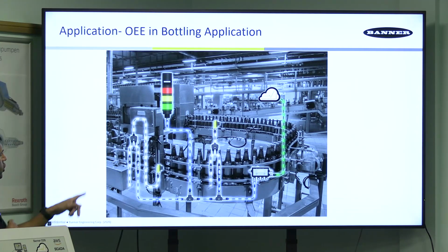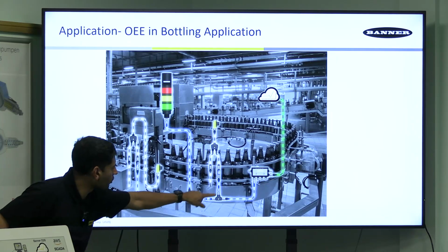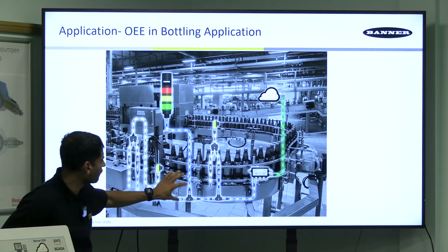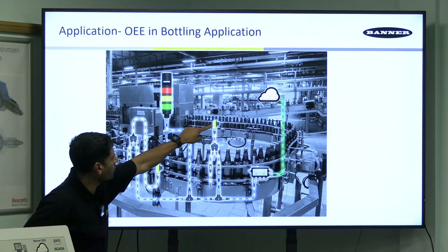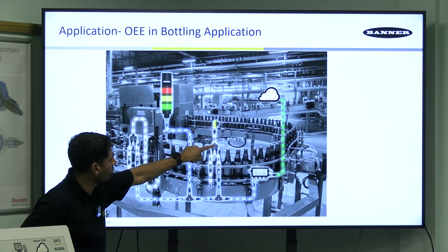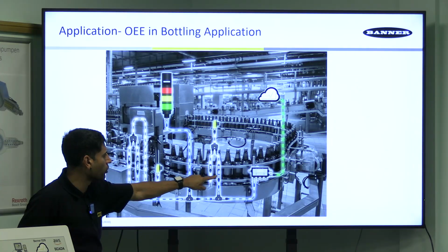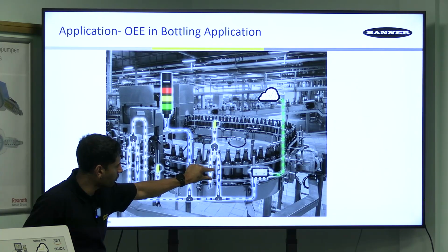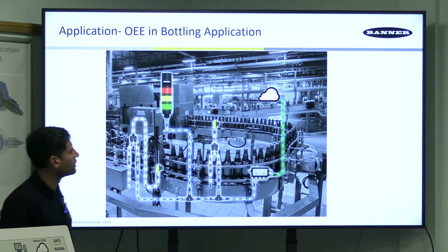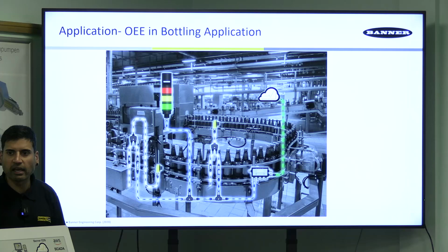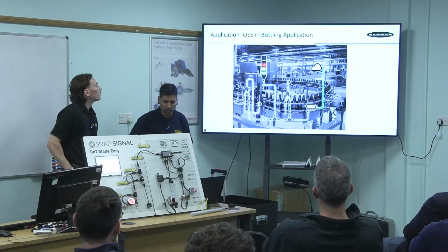And again, same sort of topology. We just take in the signal. That's a Modbus signal. That's a Modbus light. So we don't need any converter. We're just splitting it off. This is a discrete signal. So we're going to take that discrete signal, which is either on or off, convert discrete to Modbus, and then from there, using one of our little S15 converters and into the controller, we can publish it to the internet or a PLC or whatever you want to do with it, really.